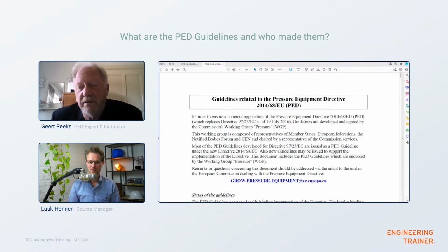But only a few tests are enough to say that you fulfill the requirements of UCS 66. There was only one problem, that the ASME code requires 20 joule at 20 degrees Celsius, or the minimum design metal temperature, which can be lower. So you have to upgrade the tests, or you have to upgrade the results to 27 joule, which is about 7 degrees Celsius.